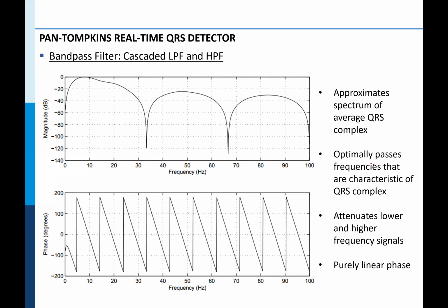Okay. So the cascading operation, which we just discussed, would have a frequency response behavior like this, and you can easily see that this is the frequency of interest that has really been looked into, with really very strong performance in the range of 5 to 15 hertz. Then it slowly starts to attenuate after 15 hertz, but it really does a good job in the range of 5 to 15 hertz. And no doubt the filter is also behaving in a linear phase.